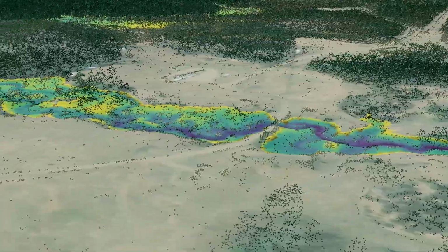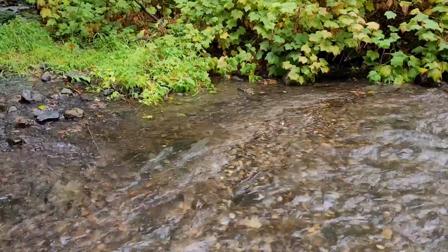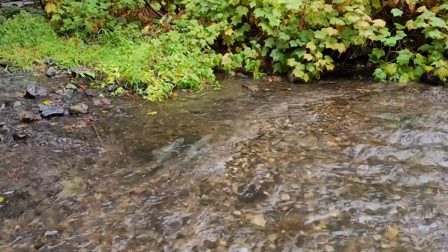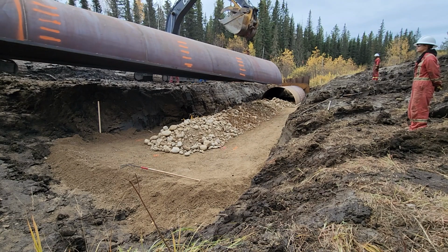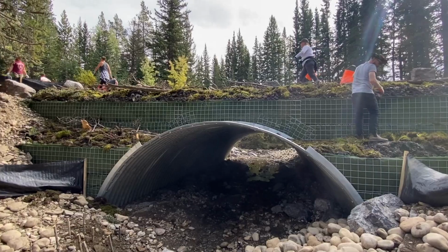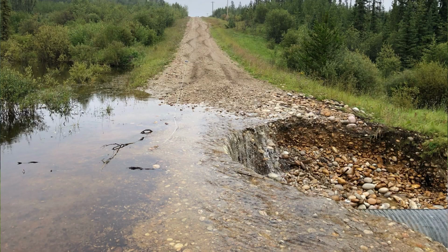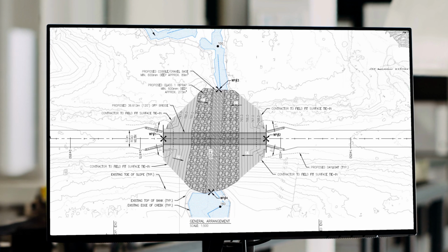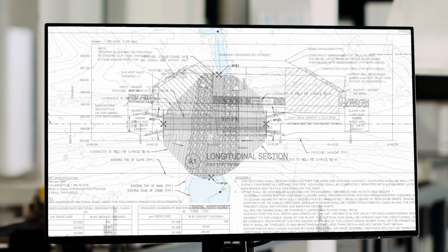Hydraulic design is the process of calculating the capacity of the watercourse crossing structure to accommodate stream flow and fish passage. It is also required to select an appropriate type of crossing and its configuration. Hydraulic design is necessary to make sure that the crossing functions as intended, to pass water, fish, and avoid a road washout. Hydraulic designs are normally completed by a hydraulic or hydrotechnical engineer for two important reasons.